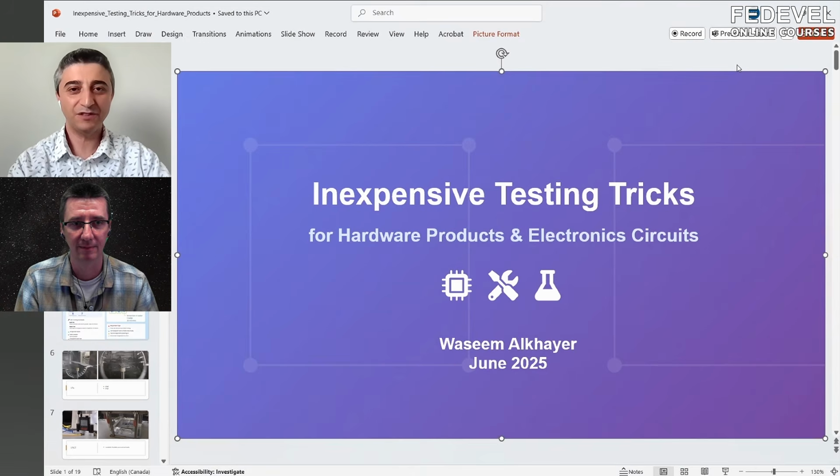So you don't have to feel limited because you're not a small company; you can do this. Yes, of course you can do it. If you are on the discovery stage or the alpha stage of your product development, you're still validating your design and your engineering. This is the time you can, as you said, put a circuit board in a freezer and subject it to maybe negative 20 degrees Celsius or down to negative 30 degrees Celsius to find out if there is a component in your design that might get stuck. A memory that might be jamming and not responding to commands, or a battery that is not able to charge, an oscillator, or an actuator that's getting stuck.